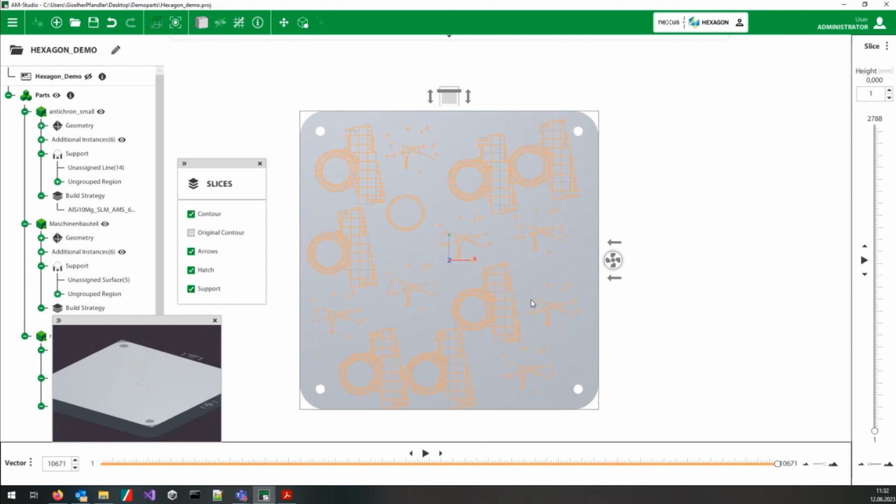As you could see, it's a really quick one. What is more, it also works that well because we were using instances. Otherwise, the slicer hatcher had to calculate every single part, and now we have only 3 parts to be calculated, and the others are copies. That's the main advantage of using instances. I think it's worth mentioning again.